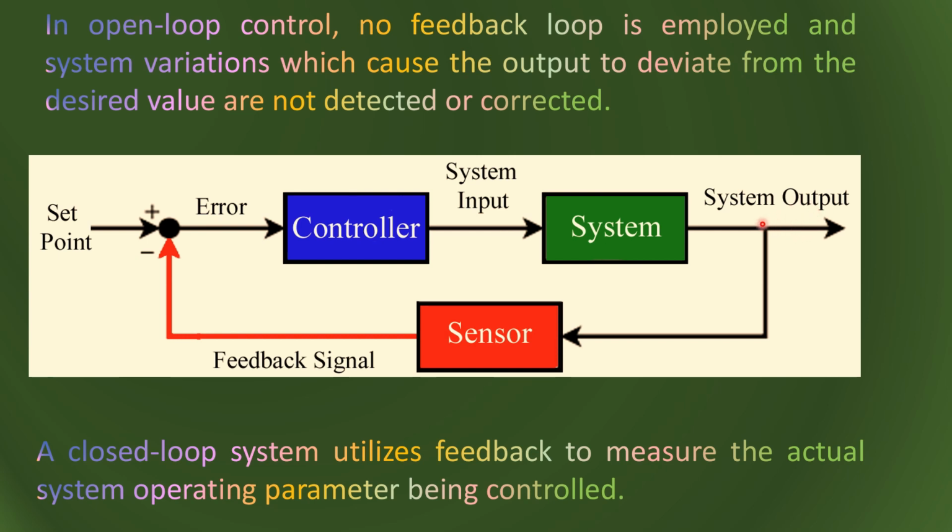We measure the output of the system by using some measurement system, which is a sensor and the signal conditioning circuitry. The controller normally synthesizes the control input to the system. So whenever we have a PLC, the controller synthesis process or the computation is implemented inside the PLC. So this part is inside the PLC, this is outside the PLC, and the set point is also an input field signal. The sensor signal is also an input field signal. But if you want to display the output, then we can send this to an output LCD or LED display or some other monitor.